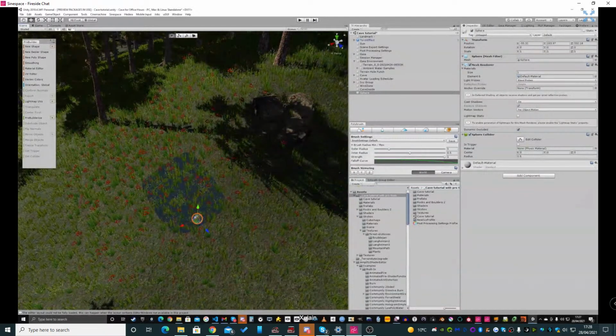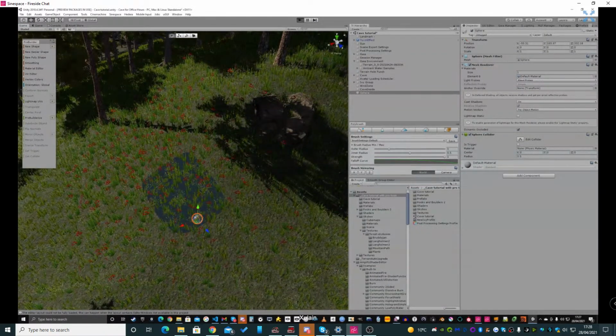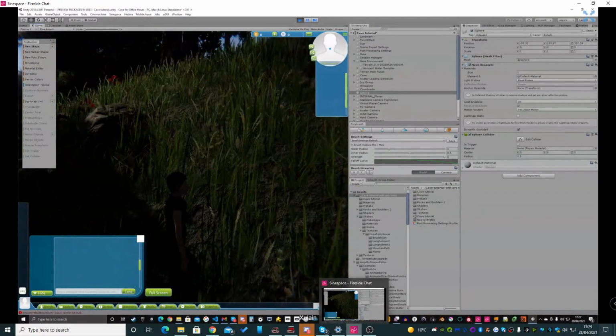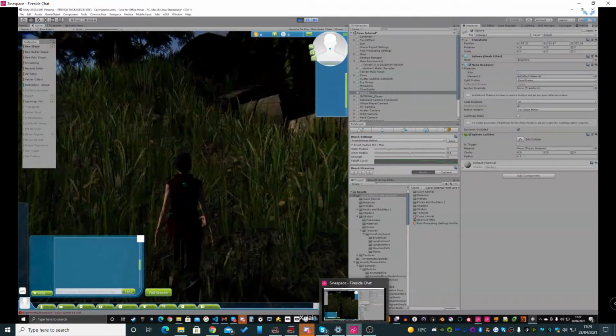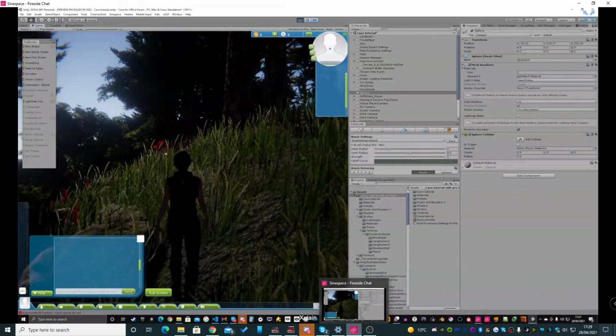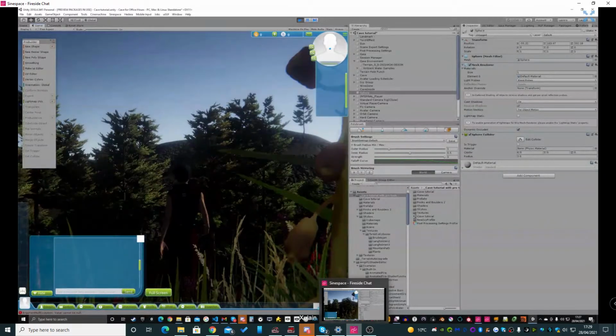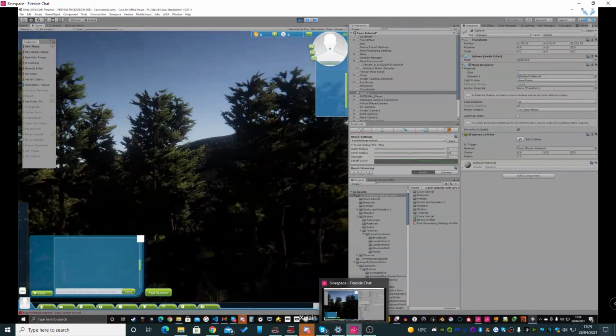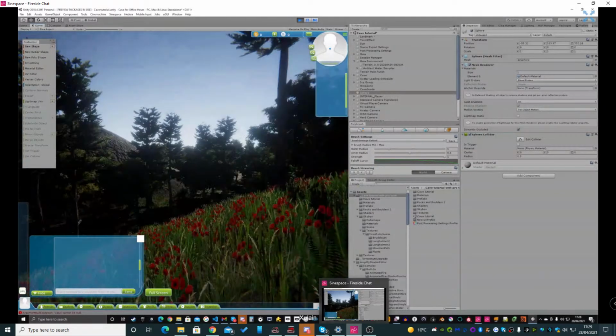But if I'm to press play now, oh, by the way, you see when I was doing that hole, I couldn't actually paint it that finely. It was like 4 blocks that it actually painted. That's because of the splat size on the terrain. And when you've upped the resolution of the terrain texture, obviously those splat sizes become smaller, and then you can paint a more detailed hole. But that's why I dress the hole, because then you don't really need to worry about the splat size.